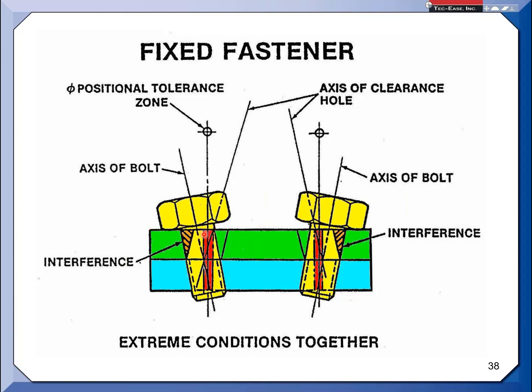And the tilt, actually, you see my axis of my bolt right now? Notice that it's outside my upper zone, which is in the plate, the green plate. The equation will tighten this tolerance so much that the axis up here will stay within this boundary. So in other words, this is going to get really, really tight to keep the axis tilting within that zone. That is an option though. So there is another equation to use when not using the projected tolerance zone. Good question. Okay. Yeah, thank you.